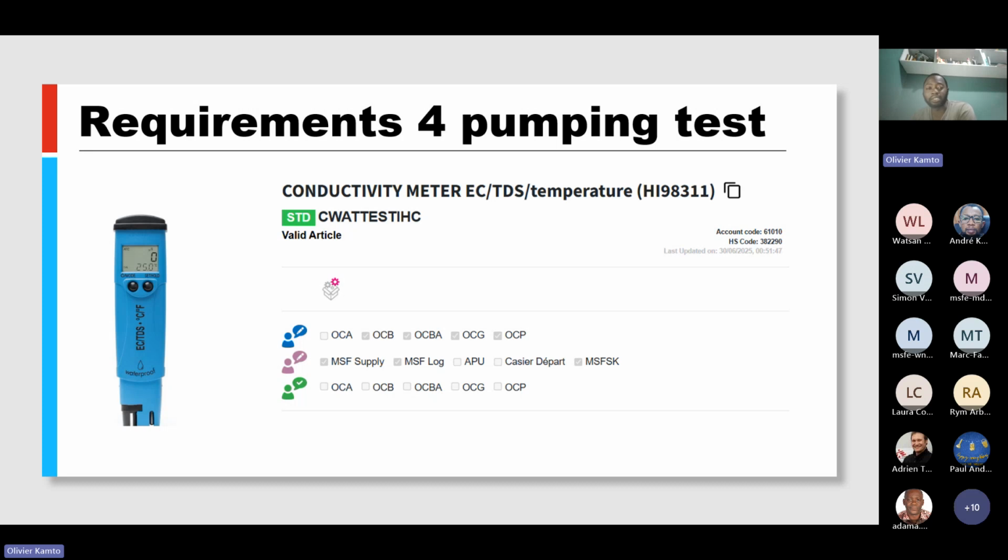And when I'm talking of water chemistry, high conductivity values may indicate presence of some salts inside of the water, or high TDS, total dissolved solids, may indicate presence of salts in the water, which may not be good, which may indicate that perhaps this water may eventually need treatment. So it's a very important parameter to try to understand during the phase of construction of developing the borehole, or during the phase of pumping test, to give us the first rough ideas of what the quality of the water may be eventually, before moving on to a lab to do a proper analysis.